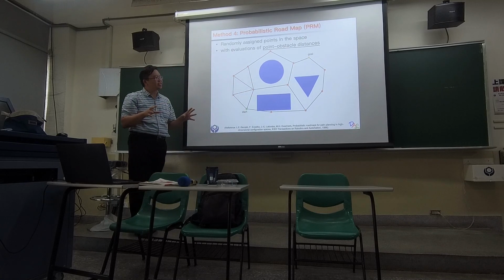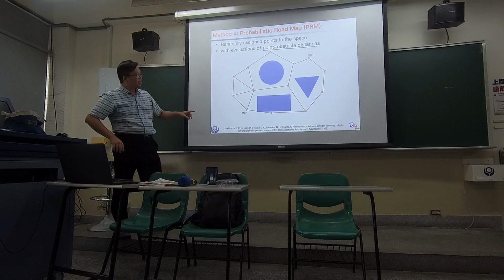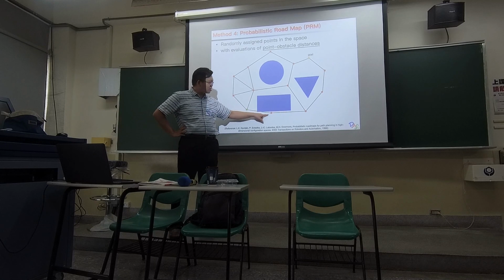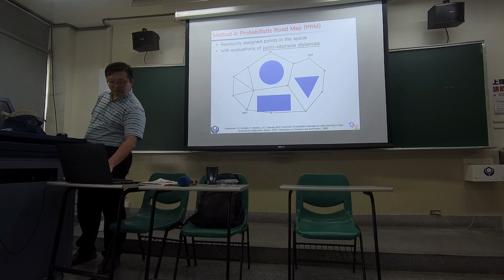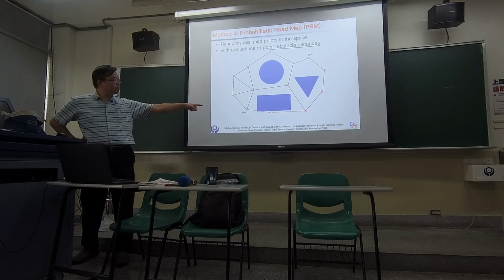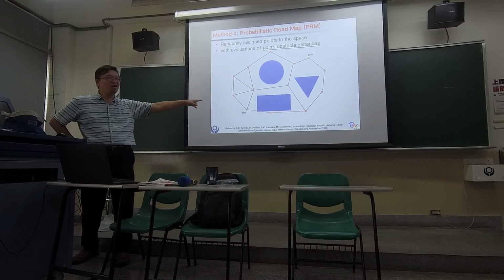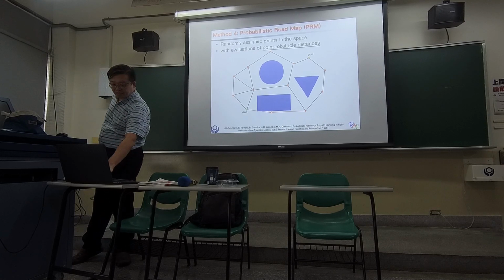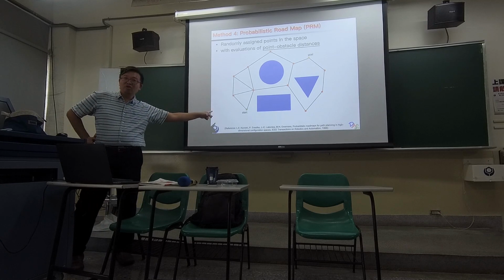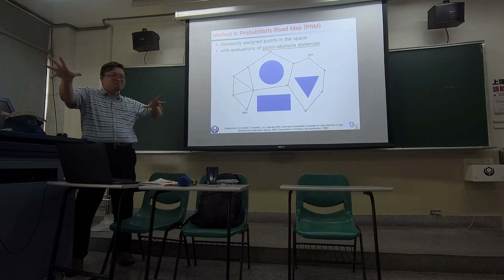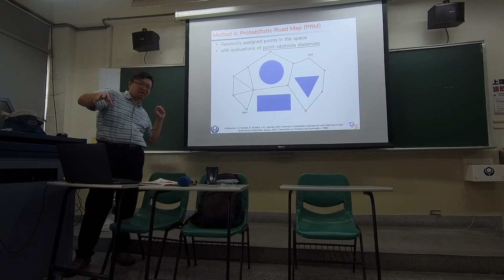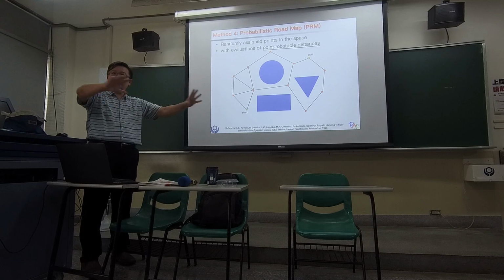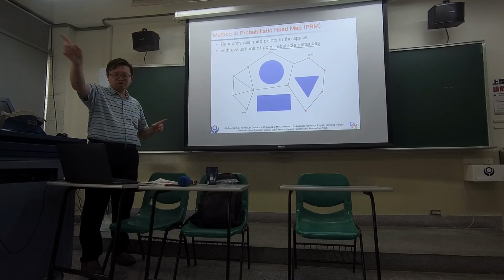Whenever they connect those straight lines, they determine whether on a specific line a collision is going to happen. So over here at the bottom, that yellow point is not a good point because it caused a collision. So that one will be removed. Once you have a network that gives a connection between the starting point and the end point with zero collision, then pick the shortest distance.